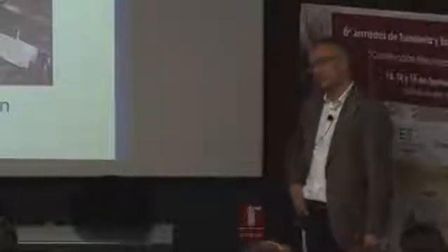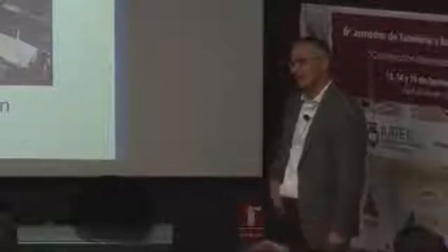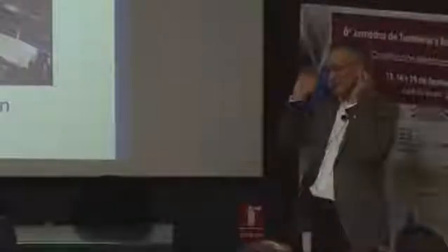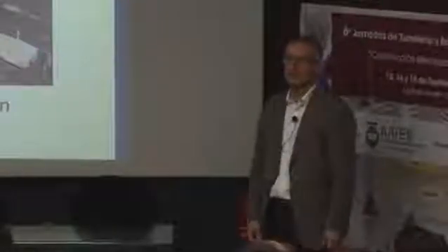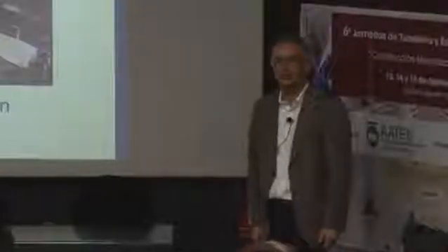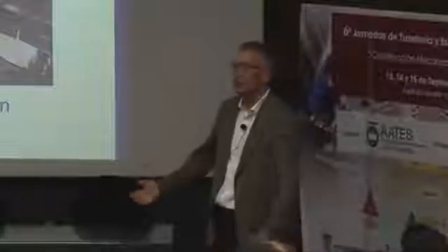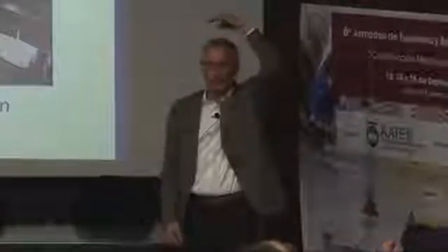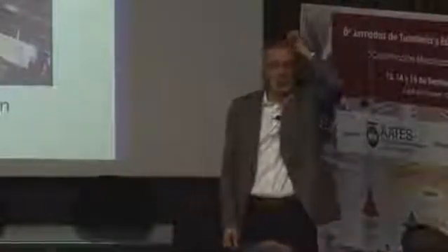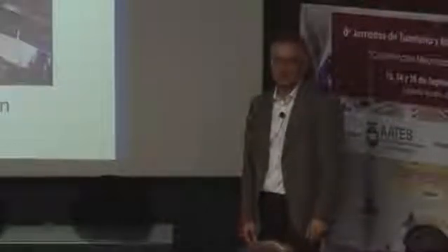Sawdust or straw, people become very creative in those moments. That has been dumped as well into the bentonite suspension, pumped into the excavation chamber. The same thing happens. It's lighter than the bentonite suspension, it swims up to the top in your cavity, and it doesn't help you for stabilizing the rest of the tunnel face.